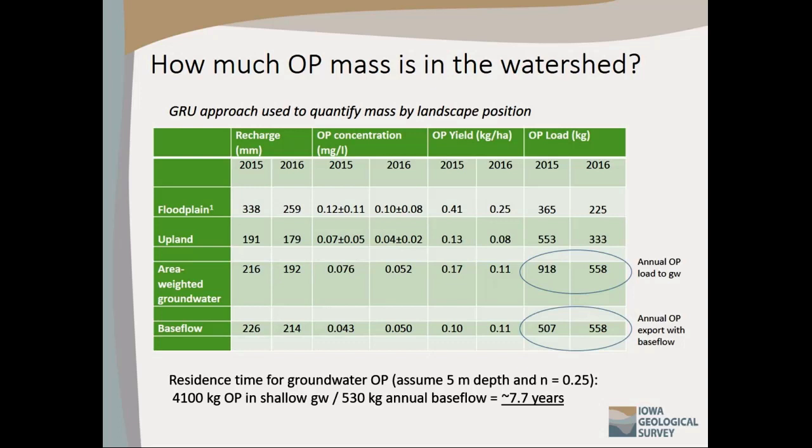So you see it there, and if you assume that that's equivalent or similar to what recharge would be, every time we're moving water through that soil profile, we're picking up phosphorus to generate that kind of concentration. So the chances are 0 that we're not going to see phosphorus being produced at the water table.